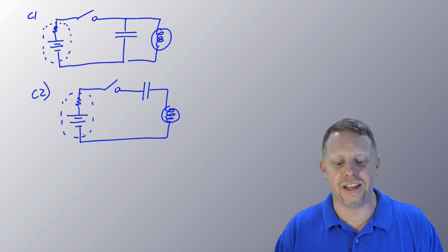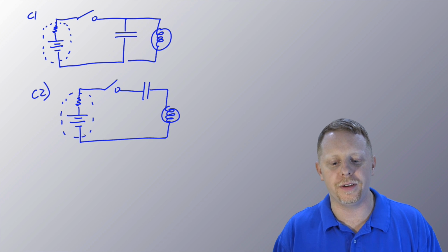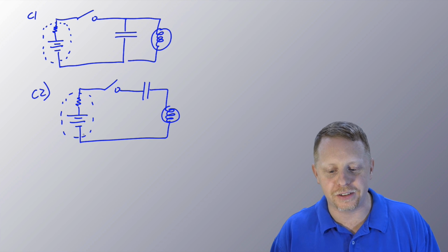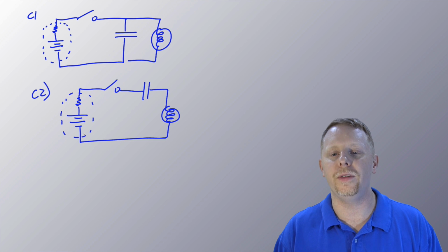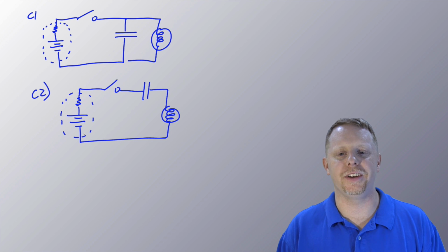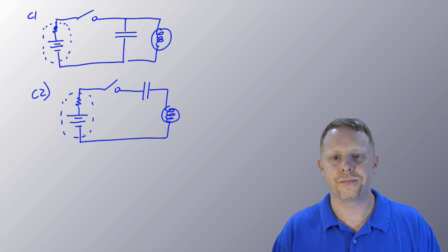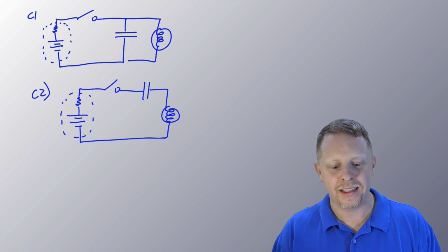From a conservation of energy standpoint, the potential difference supplied by the battery is matched by the potential drop across the bulb. But as the capacitor is charged, more and more of the total battery supplied voltage is dropped across the capacitor, leaving less potential difference across the bulb, until the capacitor is fully charged, with the full EMF of the battery dropped across the capacitor with no potential difference across the bulb, so no current flow through the bulb. Therefore, no light output. Another application of the law of conservation of energy, specifically in this case, Kirchhoff's voltage law, or the loop rule. So I think that answers those questions sufficiently from a conservation of energy standpoint and meets the circuit requirements.